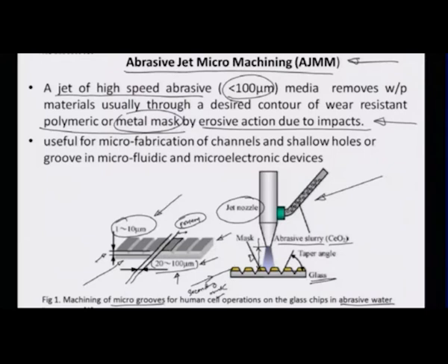D, there is a tendency, number one, for the jet to spread out as it goes nearer to the surface, which is obvious because I think we have discussed previously how important this nozzle tip distance NTD equal to D is as a function of the impact that the abrasive jet would create on the surface. Here, one important aspect is that because the mask itself is made in a tapered manner, you can see that the mask is highly tapered. Therefore, the grooves which are eventually being made on the glass, by virtue of this tapered form of the mask, are also tapered.